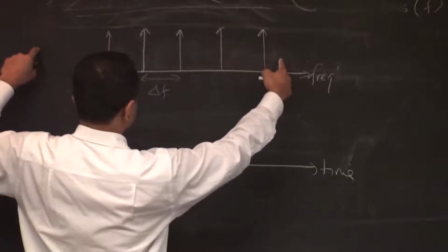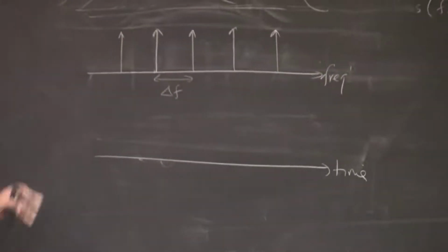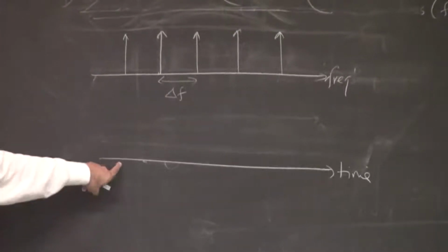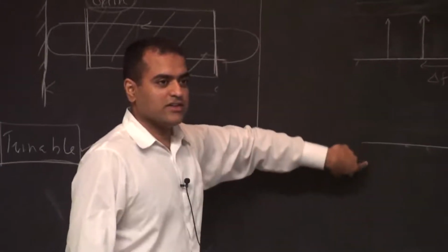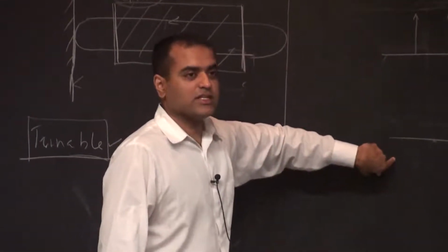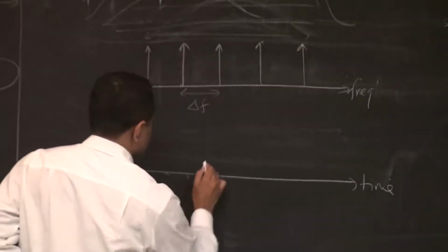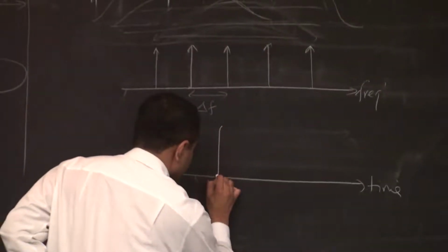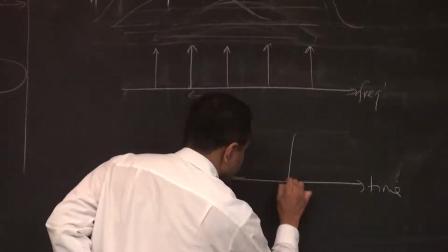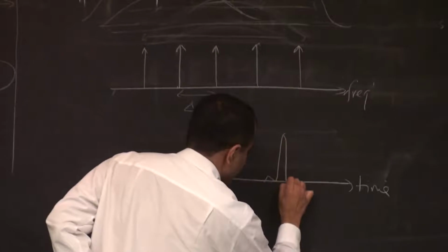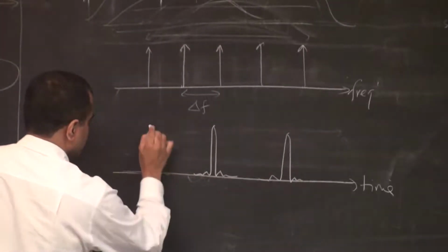But if I have what's called a Dirac comb, or a Dirac train, delta train, what's the Fourier transform of that? It's actually also a series of pulses. So if I have maybe 5 of those, or 6 of those, what it's going to look like is a very sharp pulse with a little ringing, sinc function like thing, and this is how it's going to look. I'm plotting now the intensity. I think you know that it'll go a little negative and all that too, but this is how it's going to look.